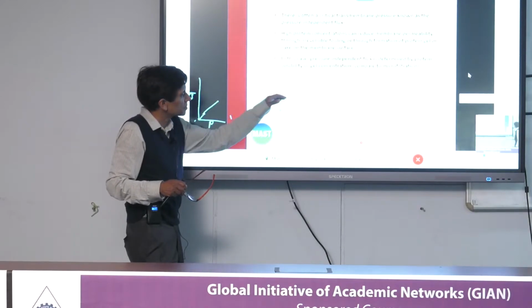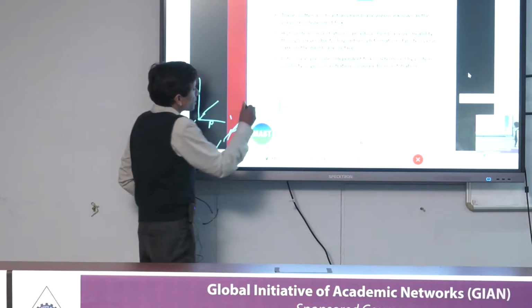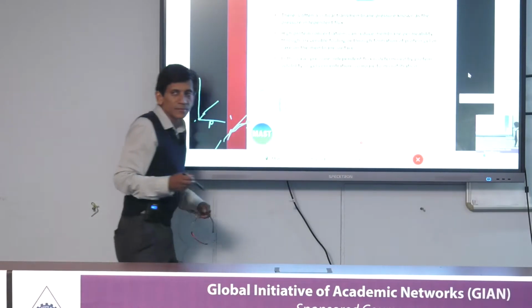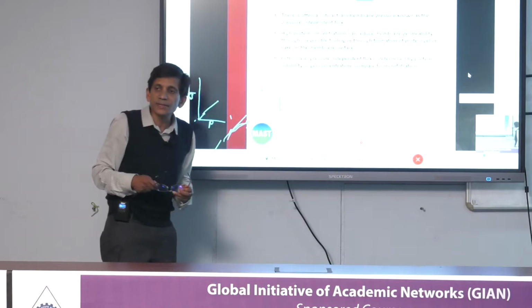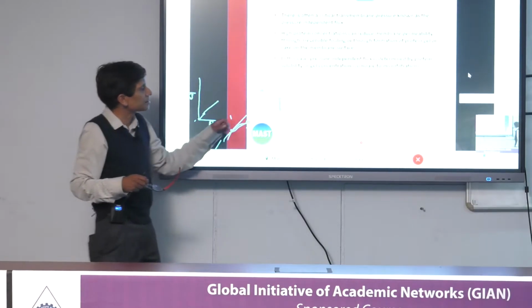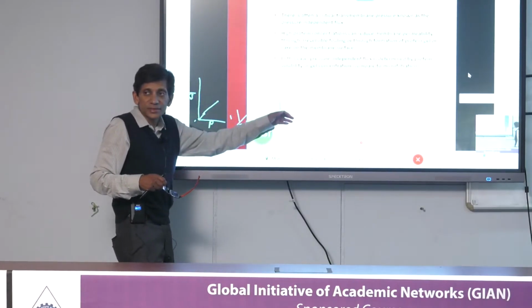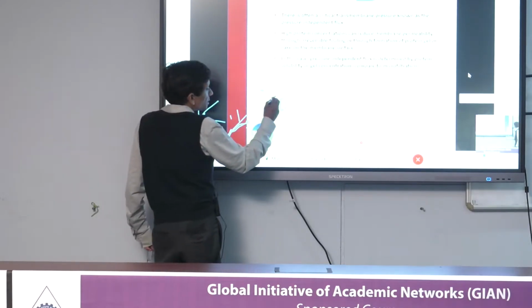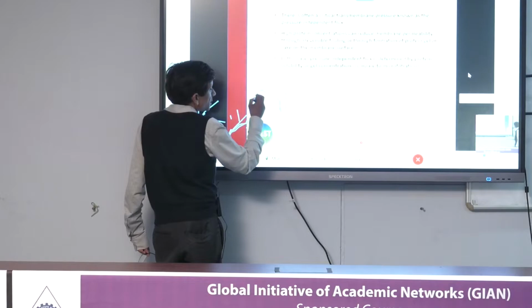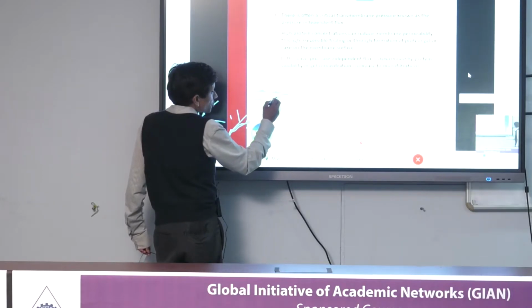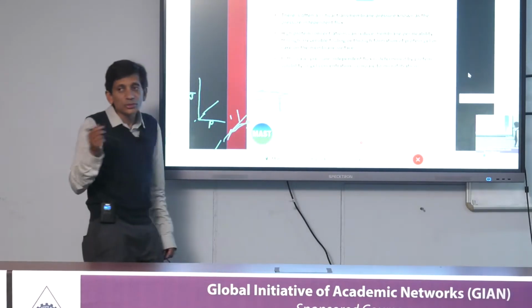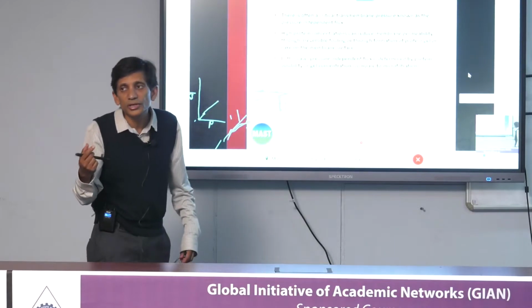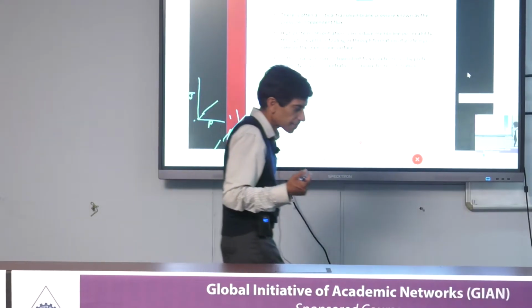That causes this concentration boundary layer and the deposited material to increase, but then I'm starting to pump faster here, but there's an overall increase. Now, at some point, as I keep doing this, you're not going to get an increase in flux, because what will happen is that may cause an increase in this layer here, but then you get a higher flow rate, which causes a decrease, and so really there's no change, and you get to this so-called pressure-independent operation.